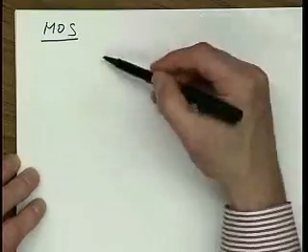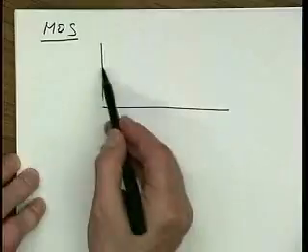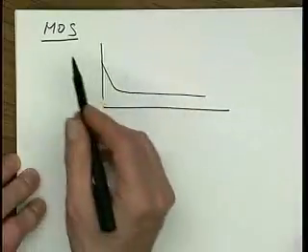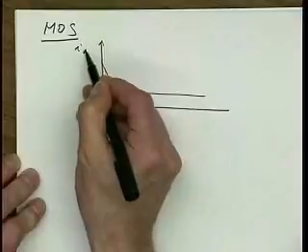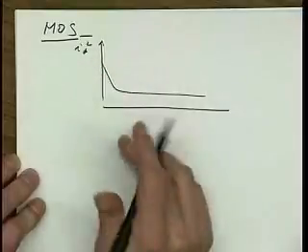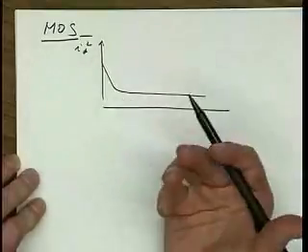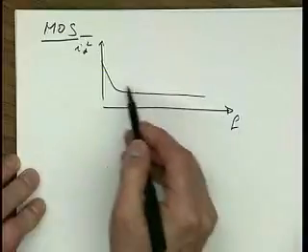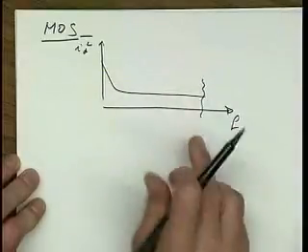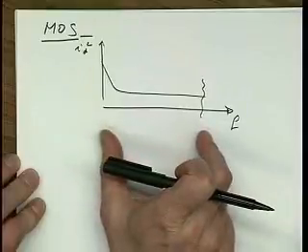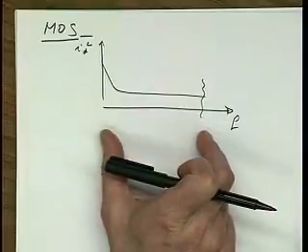First of all, because it really occurs only at very low frequency, right? If there is the sort of the total noise ID squared, and then the flicker noise, as it decreases with frequency, it may not matter. So if you have a system that has, let's say, a bandwidth of 1 gigahertz or so, why not, right?